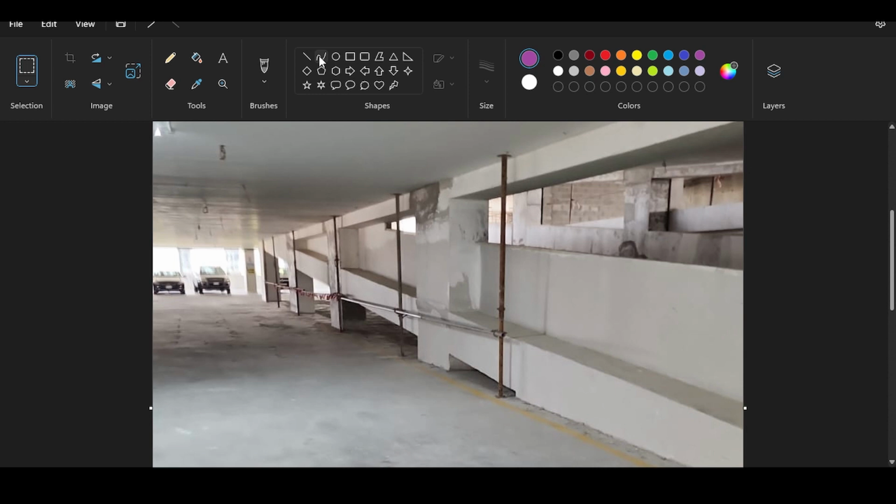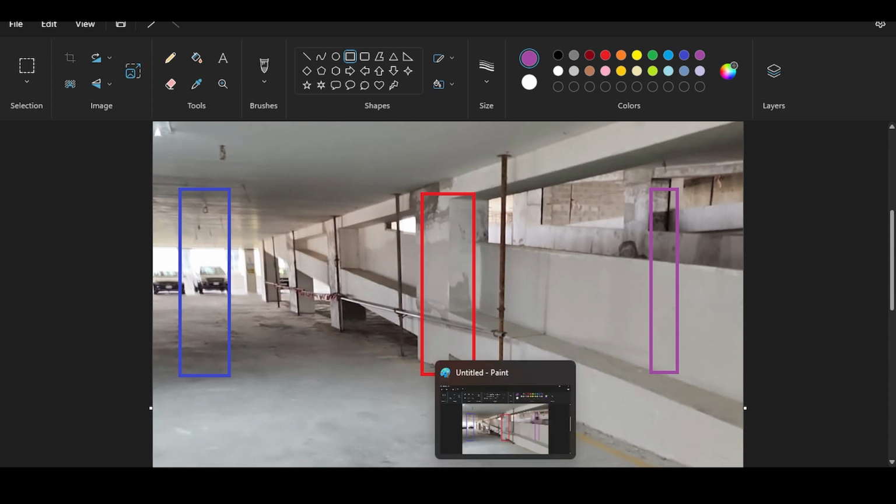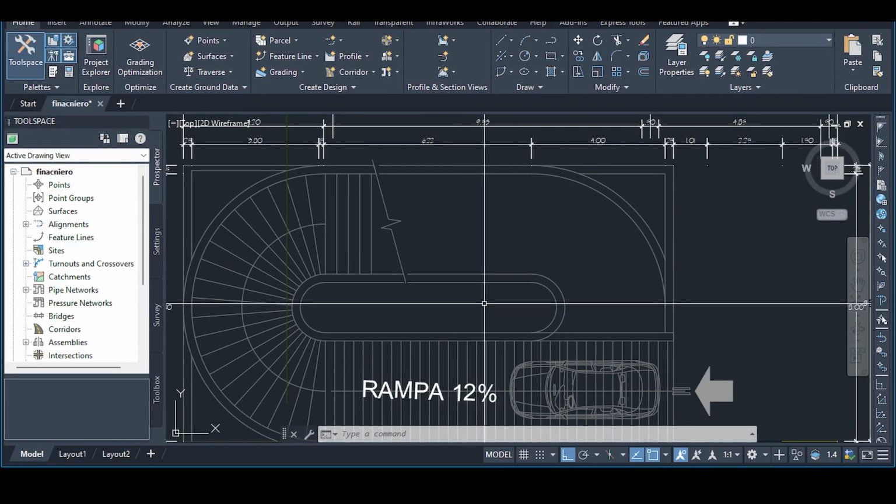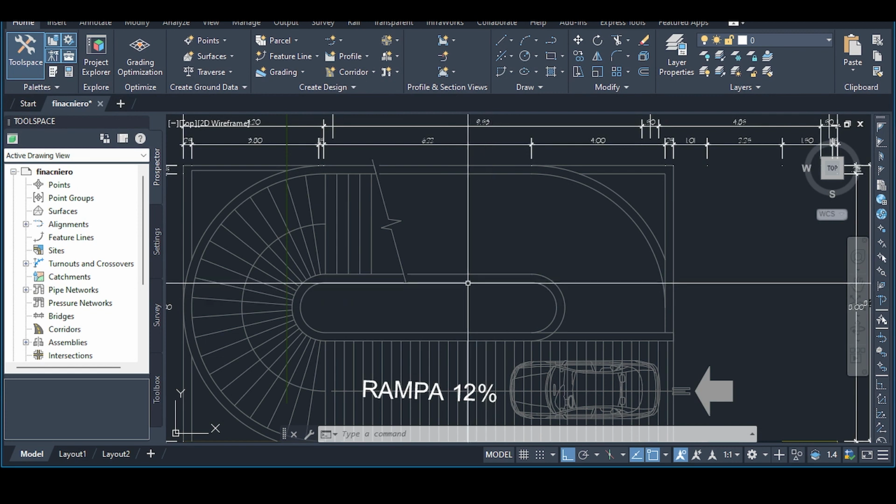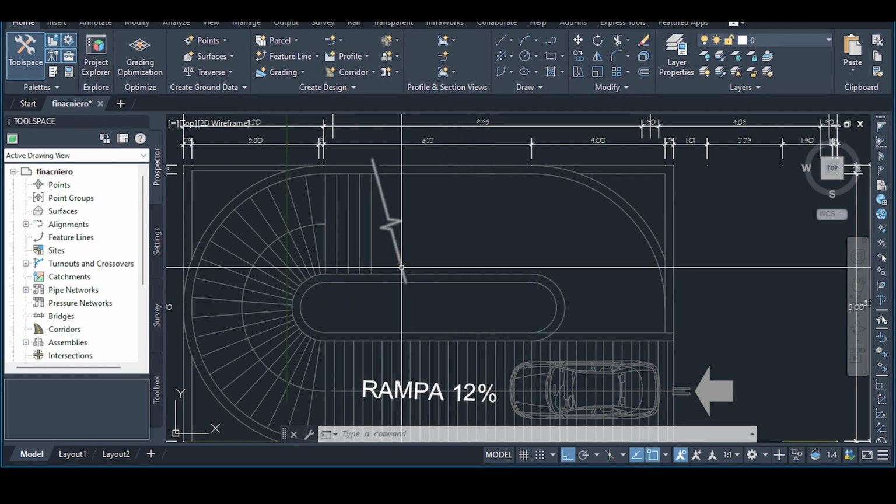You see, in my structure, I would have to have a central column. So this is a central column. And I would have a column on the side here, and I will have another column on the other side here. Of course, I'm not drawing 3D, I'm drawing 2D, but you can predict how it looks in 3D. So the central column, which I am going to plan to have here, is going to carry both ramps. So it's going to be a nightmare in casting.